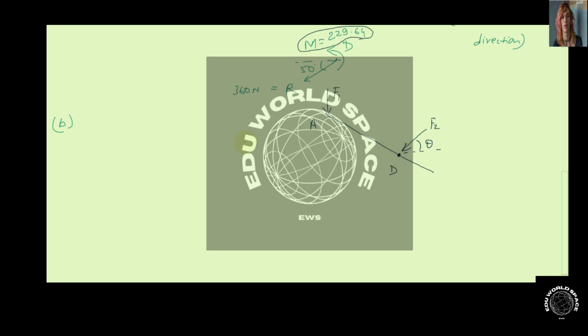So if we calculate moment about D in the equivalent diagram, it comes out to be F1 multiplied by the perpendicular distance. So this will be the line of action, and this is going to be the perpendicular distance. This length ED in the problem is given as 1.05 meter, and this angle is given as 30 degree. So this perpendicular distance will be 1.05 cos 30.